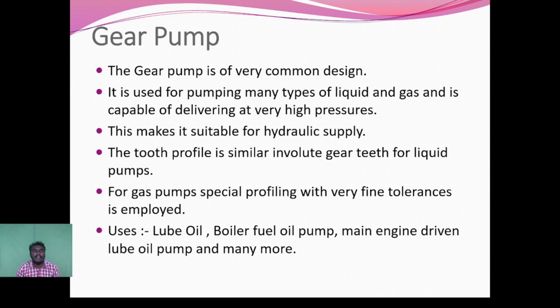Next, the gear pump. The gear pump is of very common design. It is used for pumping many types of fluid and gas and is able to deliver at very high pressure. This makes it suitable for hydraulic supply. The tooth profile is similar to an involute gear tooth for the liquid pumps. For gas pumps, special profiling with very fine tolerances is used.